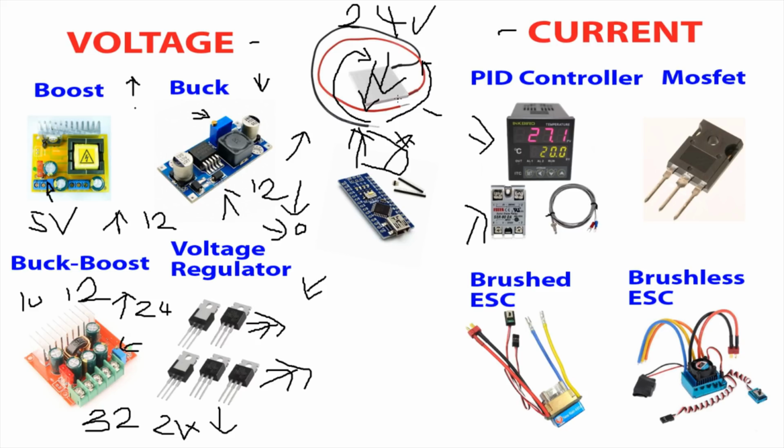So using a very, very slow frequency pulse width, you could say, this is a vague pulse width, controller like a PID is very bad for overall efficiency. And you can also say that this will result in significant thermal flux across the TEC, or heating and cooling of the TEC, which will increase the stress on the TEC by heating it up, it's expanding, and then cooling down, it's contracting, heating up, it's expanding, cooling down, it's contracting.